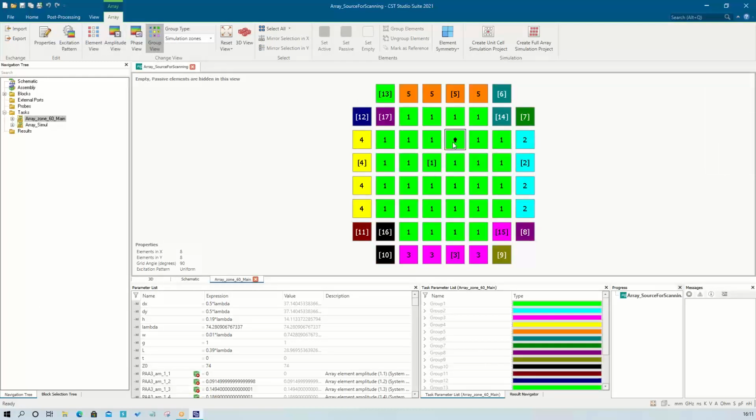Here I am also interested in the grouping. So this is the same thing I was mentioning. I have 60 elements, and if I group them, every group has a mentor. So it will need to calculate only the group mentor, because that group mentor represents the effect of all the other elements. So instead of wasting hours on simulation, you can just simulate the group member. So similarly, there are 17 groups. I did the simulation, I got the result. Or if you don't do it, then it will create the array for all the individual elements.